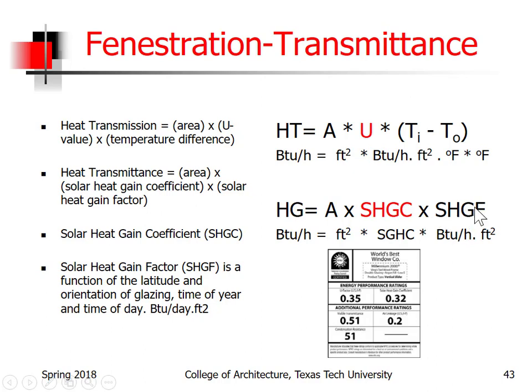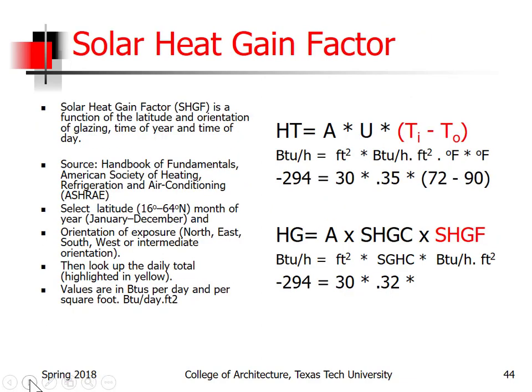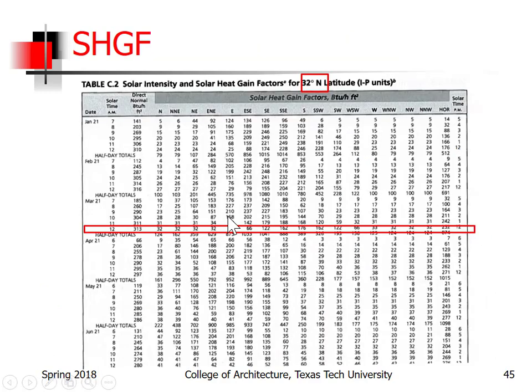And then the next thing is, of course, the solar heat gain factor. In other words, how much energy do we have coming from the sun striking that window? And to calculate that, what we're going to do is go to a series of charts. They're in ASHRAE.